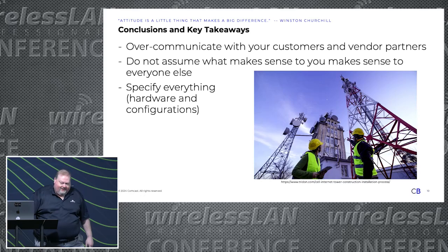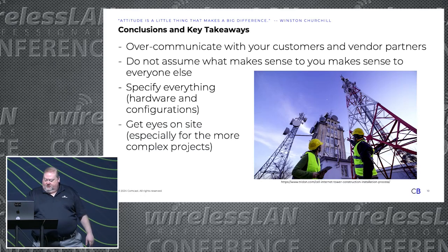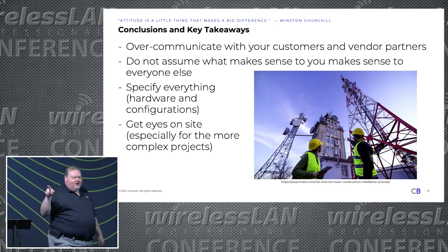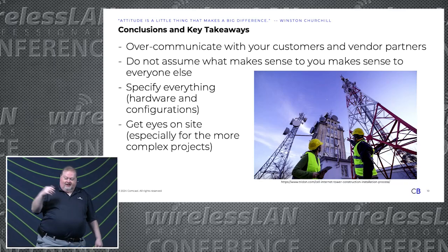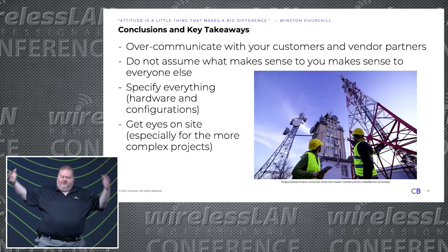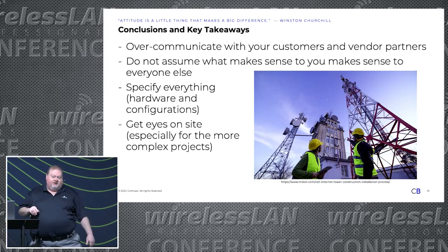Specify everything. Don't be afraid to over-specify your requirements. Now, sometimes they won't follow it anyway. Get eyes on site, especially for the more complex projects. You always see stuff. That amphitheater one, I finally got eyes on site after we were struggling with it. Within 5 minutes, I was like, that's 20 feet up in the air. It shouldn't be. I found it in 5 minutes. I did a whole survey to prove that it didn't work, but I saw the problem in 5 minutes, and I wouldn't have seen it without eyes on site.